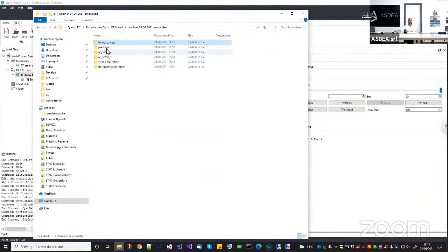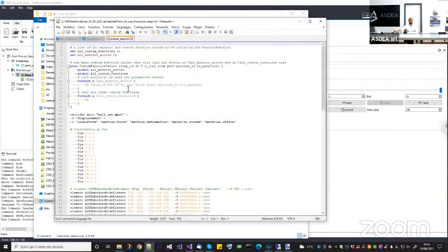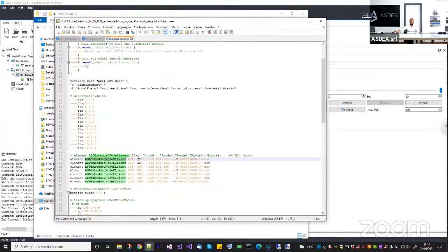If I go inside the pullout test, which is the easiest one, and I go under analysis steps, when I create the embedded element, it has the constraint node tag first, and then it can have 3 or 4 retained nodes. Now, in my case, it is a 2D analysis, so it only has 3 nodes. They are physically oriented as a triangle. So STKO gives these three IDs as the IDs of a quadrilateral, for example. Let me show you. I mean, there is not a physical triangle there.